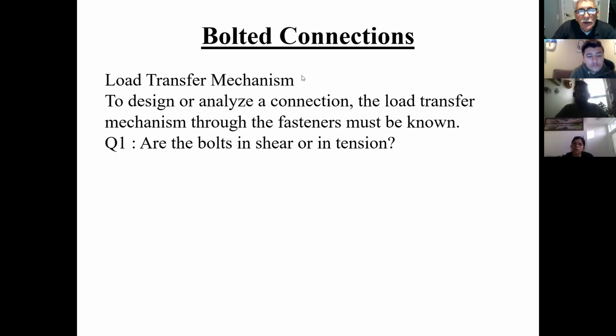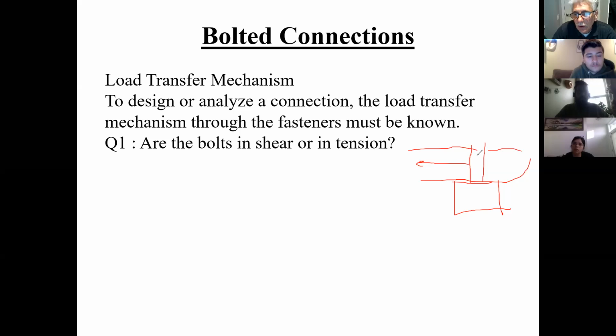Now, just so you guys, for example, let me just draw something. In other words, here's my bolt here, and all of a sudden I have something that's going across here like this, and this member is being pulled here, and therefore you can appreciate, and I'm going to take Kaylee's advice, I'm going to start changing colors, that what the bolt is actually doing is resisting this force here in shear, so that would be a shear resistance that the bolt has to provide.